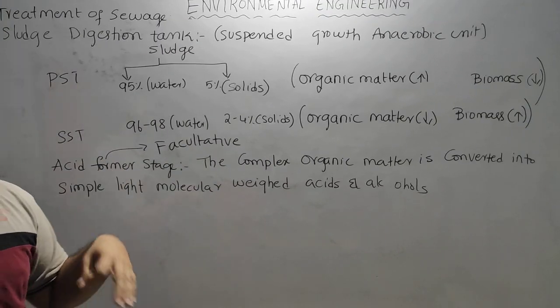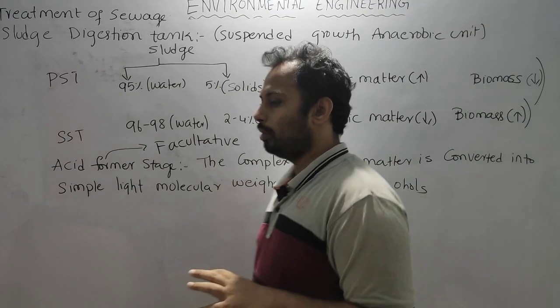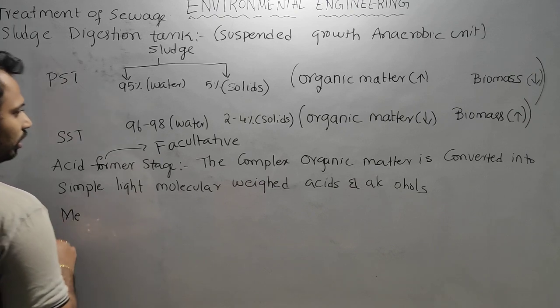When that pH changes, what happens? The methane forming bacteria will die and methane formation will cease. So that is why the methane forming bacteria should be taken care of during the decomposition.